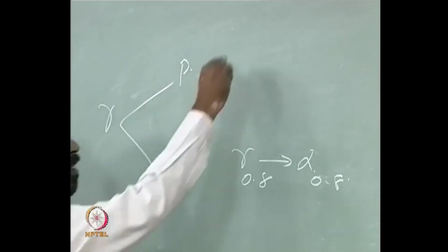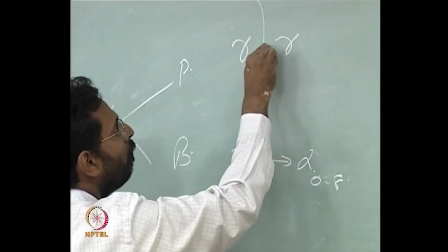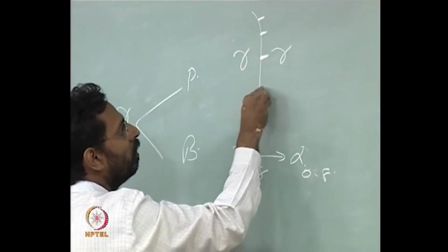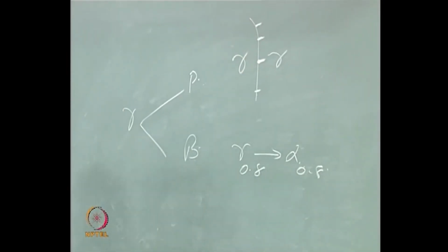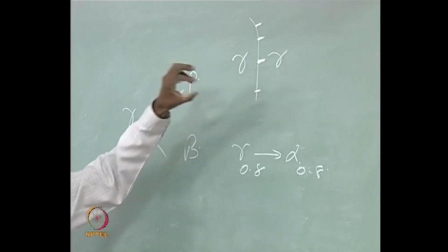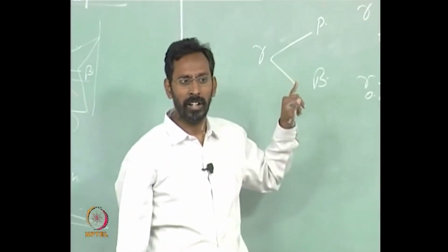Here the carbon is able to move. So what happens is carbon would come to the grain boundaries of gamma and form small regions of enriched carbon. Once that enriched carbon region reaches that of 6.67 or 25 atoms out of 75, initially the number of atoms of carbon is very small, it is 0.8 weight percent.